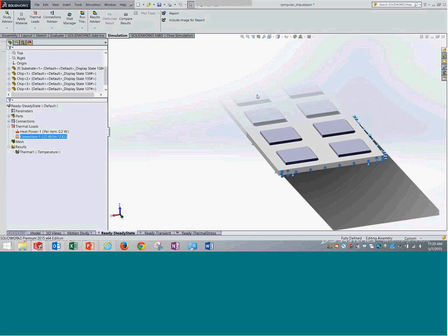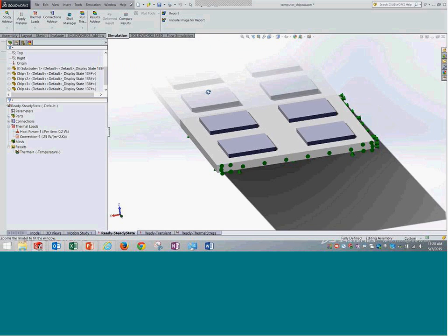Obviously, the question would be what happens to the other surfaces. The way it works, typically if other surfaces have no boundary condition, it just means that they are at an adiabatic condition. That is, no heat flows through them or comes into them. So heat is produced by the different chips, and it is dissipated through convection through those three surfaces. This is the way it is treated in thermal analysis.